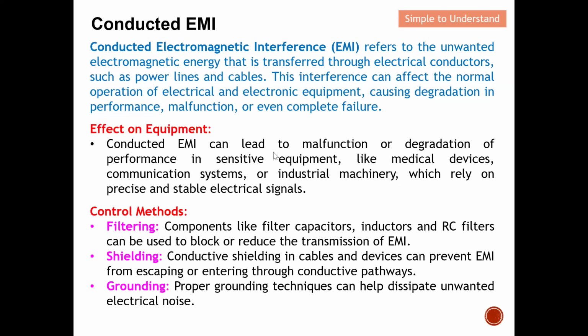Next, on the effect on equipment: conducted EMI can lead to malfunction or degradation of performance in sensitive equipment, for example medical devices. We could not afford for a medical device to fail, so this is very crucial. It also affects communication systems and industrial machinery, which rely on precise and stable electrical signals. So for this case, as I mentioned, the noise source enters through the power line or through the communication signal, etc.